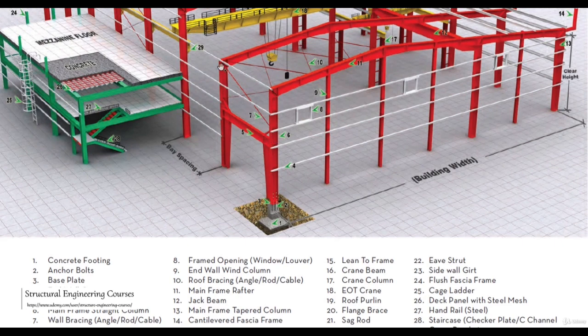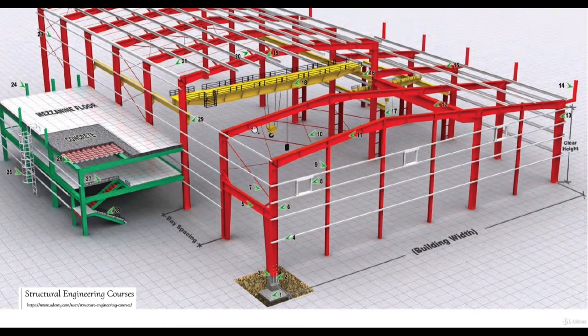Now, you must be thinking, if we are bracing this structure with the help of this wall bracing, why do we need this portal bracing? Sometimes it happens that, because all of these bracings have been made here, the designer may need the bracing here also. But there might be a case when there must be an entry from this phase. So to make an entry to this phase, designers usually provide this portal bracing.